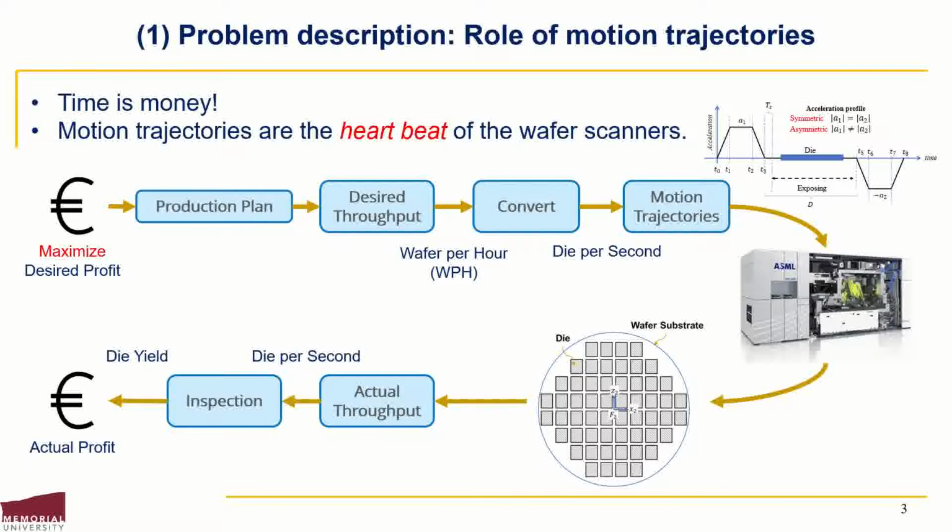Providing bounds on scanning time helps in reducing the thermal loading at the affected parts. This will ensure the performance of existing active heat controlling systems. A thermal load effect can be reduced if its duration is minimized and its period is maximized. At the actuators level, the thermal loading can be minimized by reducing the acceleration levels and by providing enough time for them to cool down.